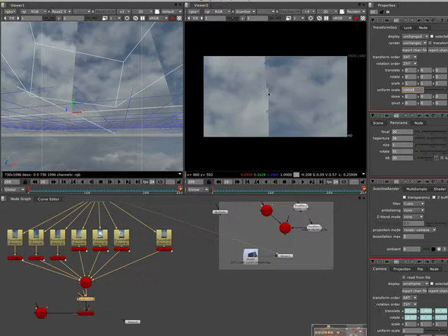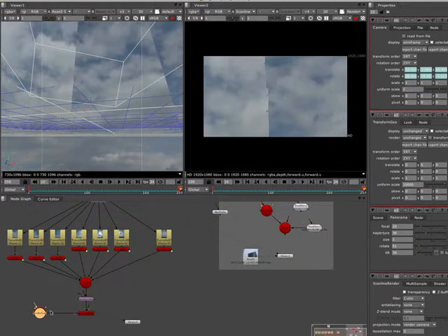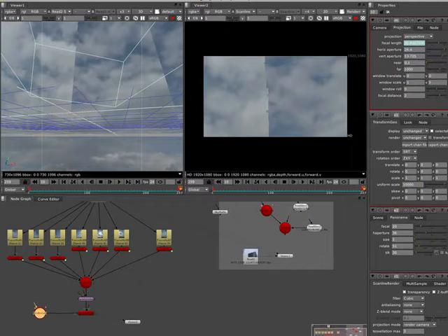Because I've got such big distances, and because I've only got a finite number of samples, there's a little bit of sampling going on. So if I adjust the near and far clip plane on my camera, just by double clicking on my camera, going to the projection tab, and just bump this up. If I do this with the output of the scanline renderer visible, I can actually see it happen interactively. So I'm just bumping up the near clipping plane on my camera. And as I bump this up, like magic, it goes away.